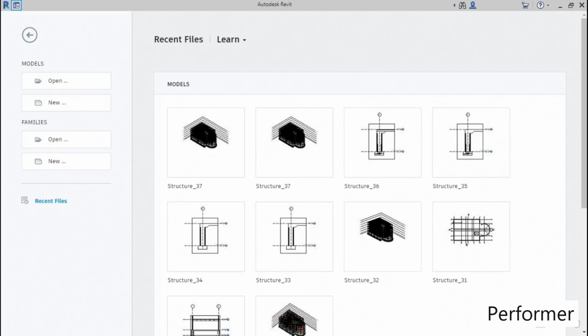What I'd like to do now is create some lateral brace frames. Up to this point, we've pretty much done everything in a 2D plan. What I want to do is put in a 3D element. However, we're going to remain in 2D. The trick is here we need to create an elevation, and we need to set the reference plane onto a grid line. Let's jump into Revit.